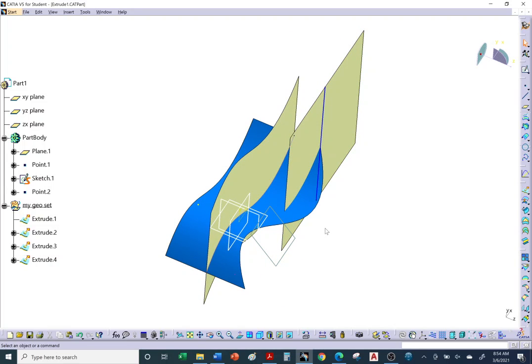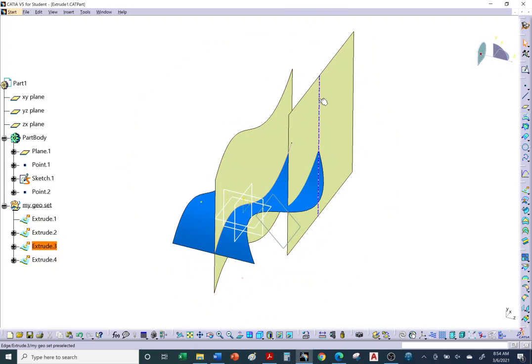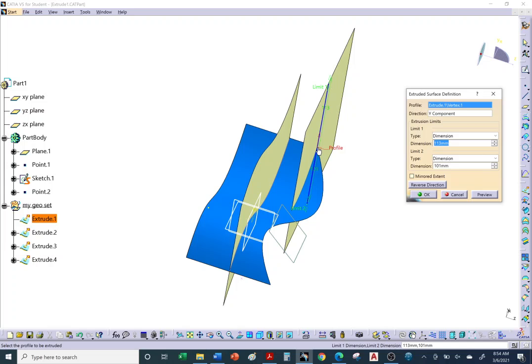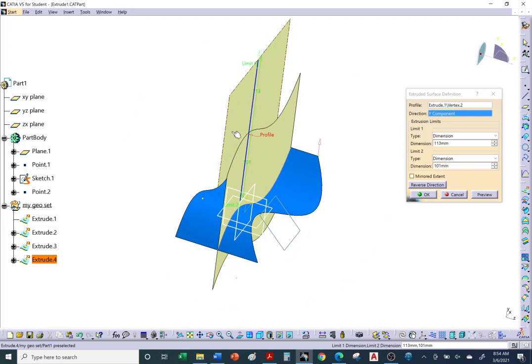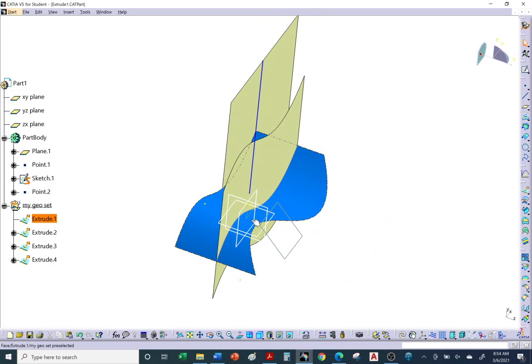Now, something that's cool about parametric modeling is it's smart modeling. Let's say I wanted to move this line over to this corner. So if I double click on this line, and instead of making this my vertex here, the original point, let's say I wanted to change my profile, and instead I pick this point. Notice how it transfers over. It recognizes a new point. It extrudes a point to create a line, and then the surface also moves with it. Pretty cool, right? So that's parametric modeling.